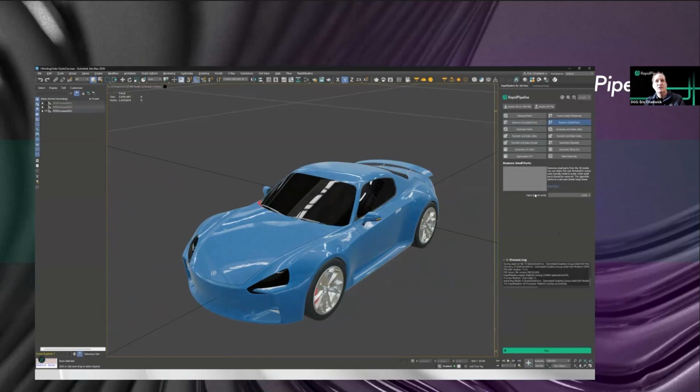So you basically choose a value in scene units, and scene units are usually, for us, in meters. 0.01, anything smaller than a centimeter by default, would be culled. And you could set this to whatever value, say anything under 2 centimeters. Go ahead and remove it. And it automatically goes through the model and figures out all those little parts it can remove. So that's culling and how it works.